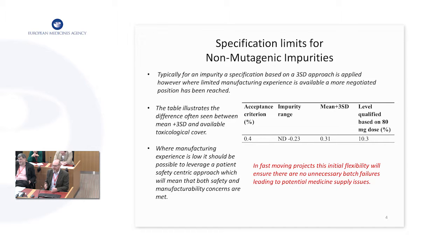What's the problem with that? Well, look at the top end of that range, 0.23, and if the limit was 0.3, that's on 7 or 8 batches. There's a very real risk that if we'd set that specification based on that limited amount of data, we could easily find ourselves, as soon as we started full-scale production, in a situation where we started to fail batches.